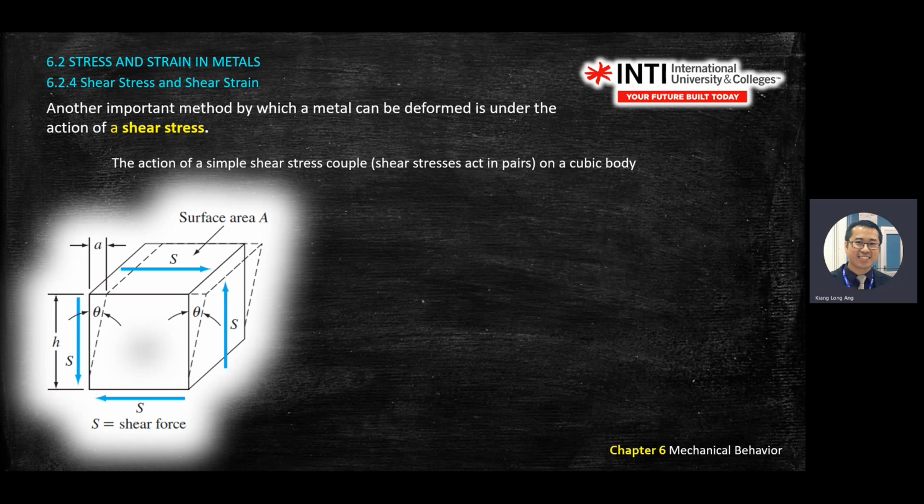Okay, so for this shear stress, try to remember, imagine this as a rubber material. If this is stuck to the surface and there is a force that pushes to the right, there is a deformation, an angle deformation from the original position to the second position, with a change of angle theta there. And there is a distance traveled by the top surface at the edge here, and H is the sample height.